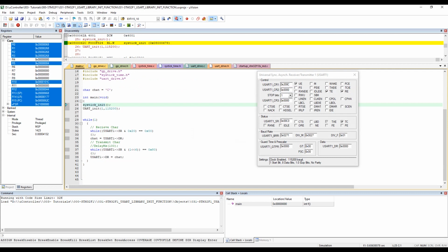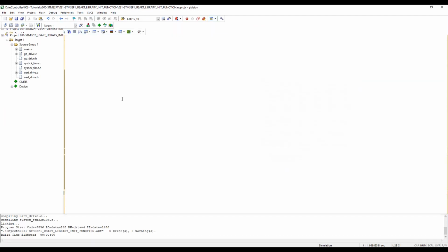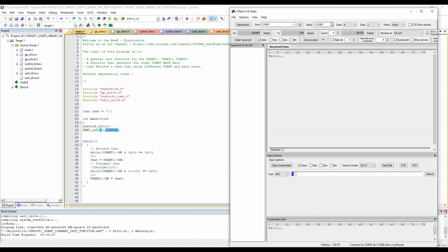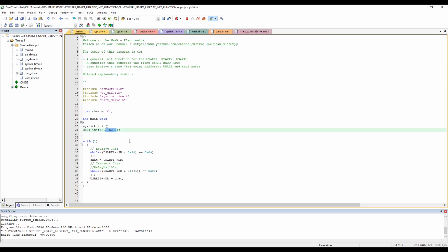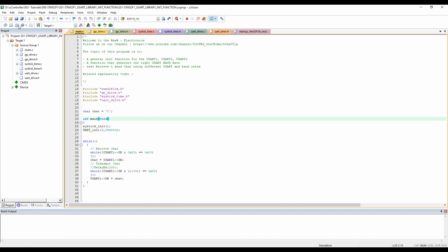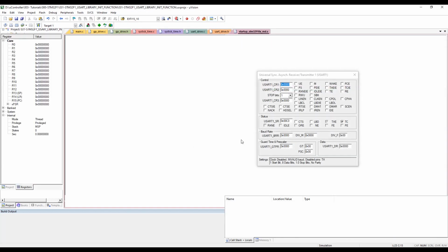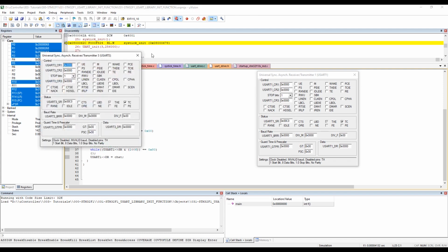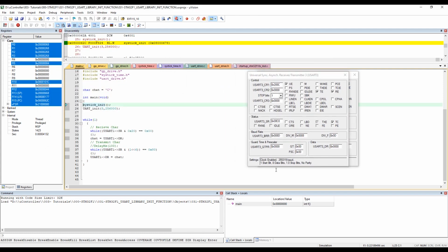Okay, fantastic. We do have now the UART1 enabled and the baud rate is correct. So let's make a last test for the UART3. Yeah, quite a lot of fun. So we do have a function that immediately calculates the UART that we need. Let's take any other. Yeah, let's take a 256,000 baud rate. Okay, so let's save and use for UART3, build and take a look. Okay, so we don't need UART3, but we would like to see the UART, no, not UART1, but UART3. Let's run and see. Okay, so we do have a 25,000. Yeah, that's a good baud rate and it's enabled.